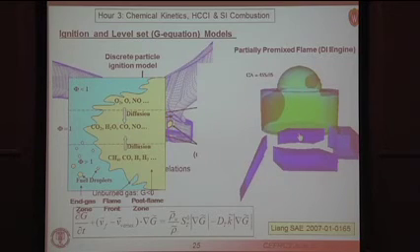The G model, as I said, allows you to keep track of the interface between the unburnt fuel and the burnt fuel. It actually applies over the whole range of equivalence ratios from rich combustion to lean combustion. And behind the flame, we can have diffusion processes occurring. So basically, all modes of combustion are possible with this strategy. The location of the G surface is determined by this turbulent flame speed and the propagation process of the G equation itself.